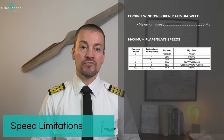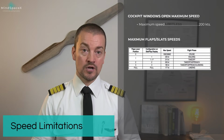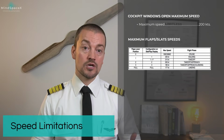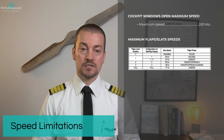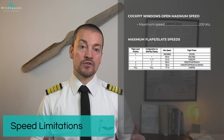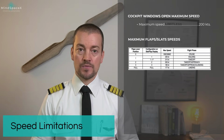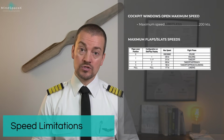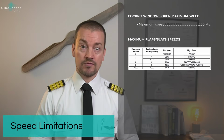Maximum speed with flaps 2 selected and extended is 200 knots. Flaps configuration 3 is 185 knots. And config full is 177 knots. Always make sure you know these values as they are very important to the limitations on the aircraft.